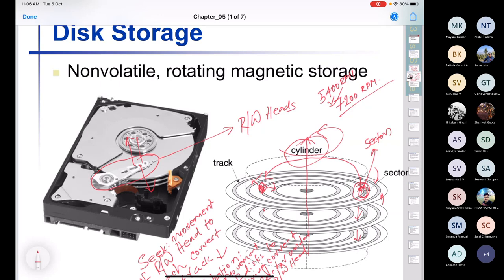So you could have said, okay, why not push down the output of the DC adapter to 3 volt? Then the entire thing will be operating at a very low voltage. You cannot. Your microprocessor maybe and some other electronic chips might be able to operate at 3 volt. But these electromechanical things or even the flash memory, probably it needs to create a large electric field to cause read and write of data.